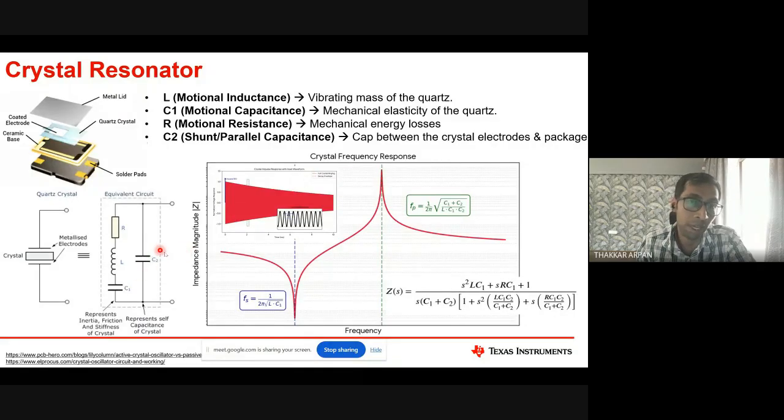You understand? So that's why even if you take this circuit and try to connect it outside, if you take a crystal's data sheet, they say that the load capacitance on this network cannot be higher than something. Let's say they will say that your load capacitance cannot be more than 50 pico or maybe 50 nano.